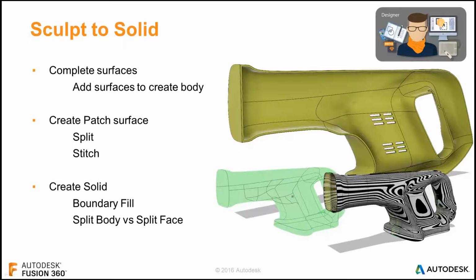What we're going to do now is start transitioning into, for the next hour or so, this free-form body. We will complete the free-form body and then move into the solid world, so we can take advantage of the traditional solid modeling tools to augment the design. We will be adding more surfaces or T-spline bodies, again bringing things together. We will also take a look at a couple of new tools and a couple of new approaches versus drawing the basic primitives. Then we'll go ahead and create a solid model from all of these faces and surfaces.